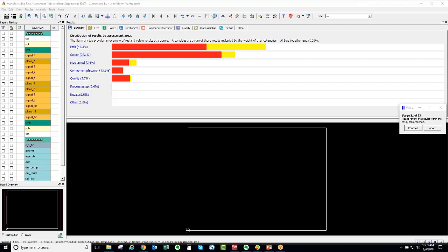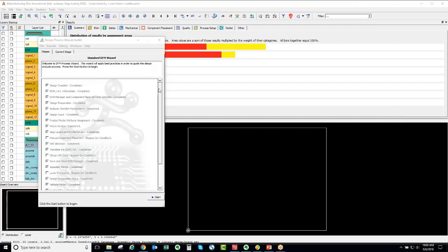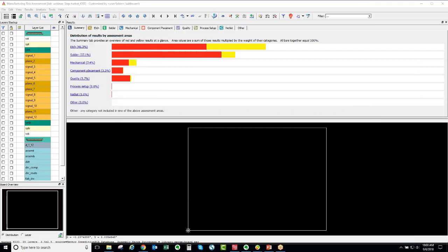If you do find models from Mentor that don't seem to be right for some reason, they have a mechanism for reporting that this model is incorrect and they will go fix it. So if you are seeing models that don't look right or don't match the specification for a particular manufacturer's part number, by all means, please contact the Mentor Valor group and have them fix those parts.